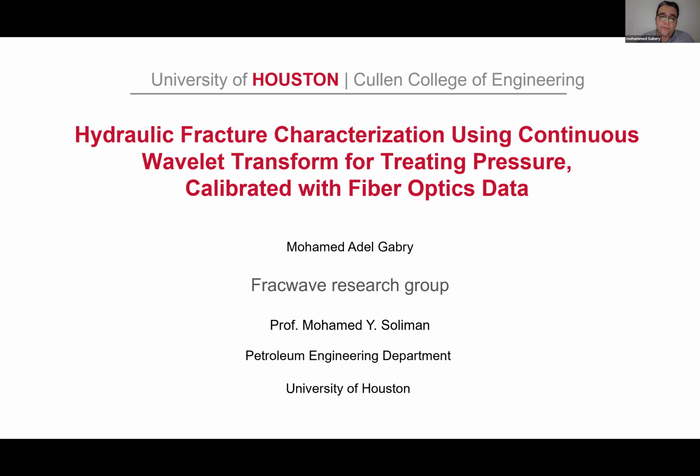But from a calculation point of view, it can be done in real time, as it doesn't take long in computation, which could otherwise be an obstacle for real-time application. So each hydraulic fracture job has its own minimum and maximum, but we mark the fracture propagation signature based on the minimum and maximum of the previous treating pressure points.